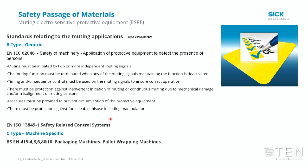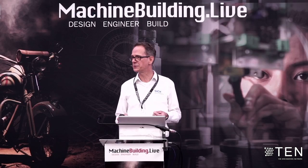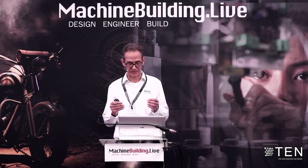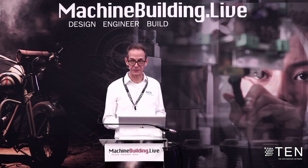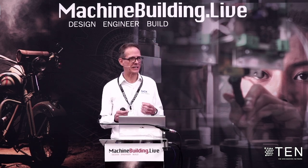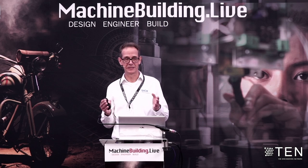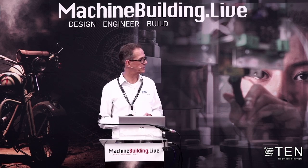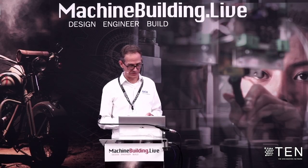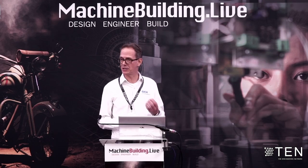The muting function must be terminated as soon as any one of those signals becomes deactivated. The timing or sequence monitoring of muting signals must also be checked and maintained throughout the mute process. There must be protection against manipulation or mechanical damage to the muting sensors such that you can avoid a permanent mute situation. And this is usually achieved by time limiting the muting on the light curtain or access point to avoid a permanent mute situation.